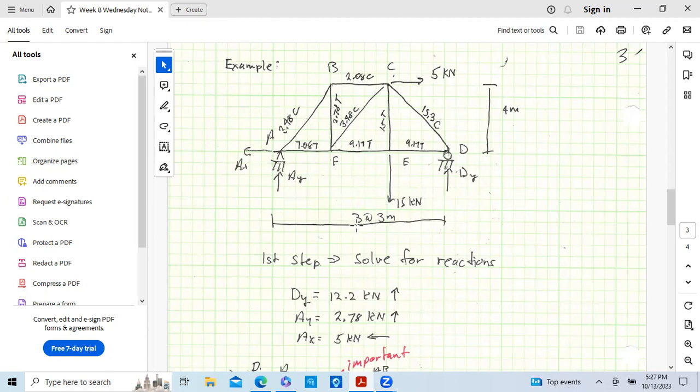What this says is 3 at 3 meters. This means there are three bays, and each bay is 3 meters. So this is 3, this is 3, and this is 3. If there were 10 bays, it would be 10 at 3 meters, 10 at 5 meters. Much more efficient than repeating it 5 times as a dimension.